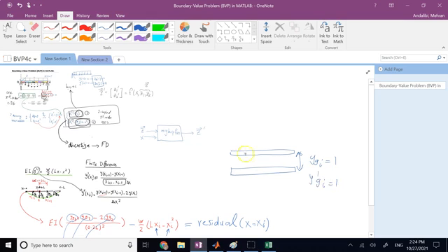If that's the case, then this is not going to be the shape because you also have a slope here. So your equation is basically going to be a slope plus 1, so your beam has to end up like this. It has a slope of 1, and then everything goes down by 1. So your y of x, the solution, is something like x plus 1, correct?